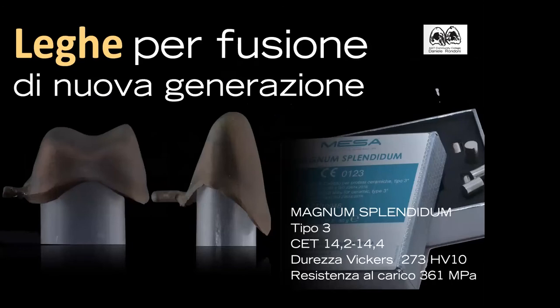New generation casting alloys. I use Magnum Splendidum. It has a very interesting CTE, a very stable alloy during firing, and load resistance. Vickers hardness 273 HV10 and load resistance 361 MPa. It has excellent load resistance, and I can use it in many different ways. It is excellent.